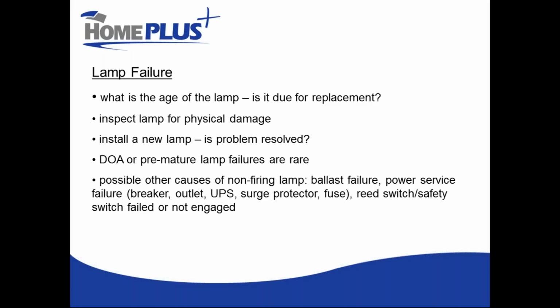Yeah. Sean had a couple more questions there. I'm going to try and tie them all together because it's sort of similar. So he said his meter reads free chlorine in ppm. What is the equivalent of 0.4 to 1 milligram per liter in ppm? And then he says he Googled it and they're equal.